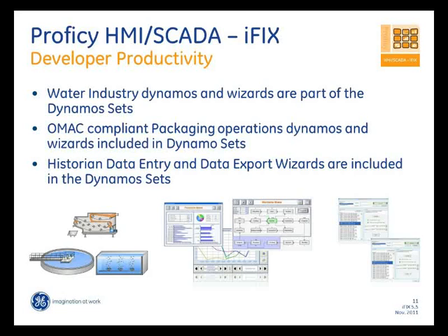You have certain pre-built screens that get installed as well, which are geared towards a packaging operation with a chart object, and these screens were pre-canned to accept OMAC compliant registers from different PLCs. So if you use a PLC that has a configuration as per the PackML standard, you can tie it into these graphics, and these graphics have been pre-canned from an animation perspective to accept PackML states and animate themselves. So that's already part of iFIX 5.5. It's a default part of it.